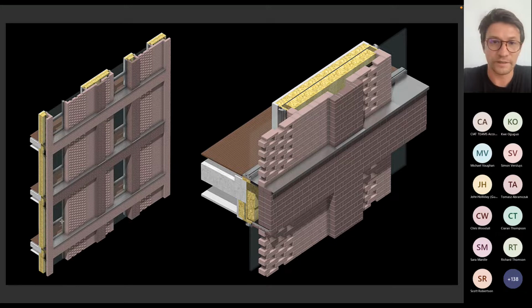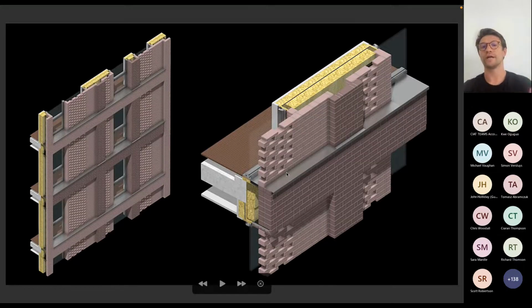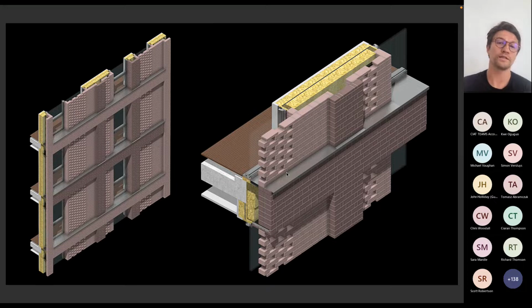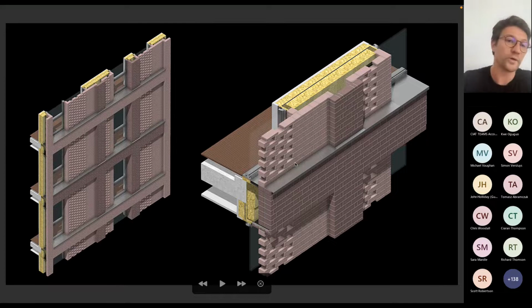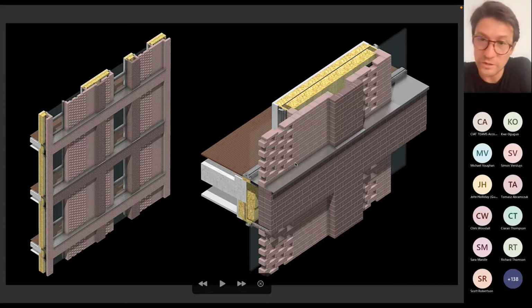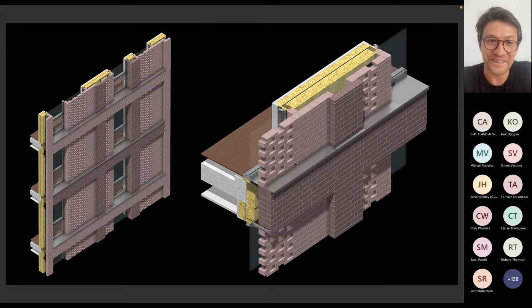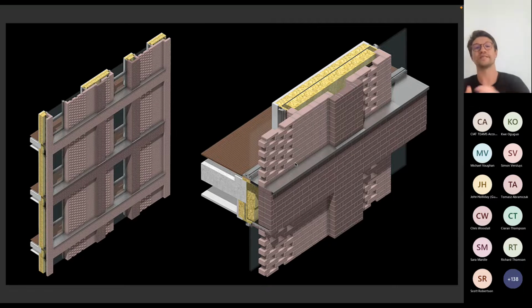I just added this slide here for one simple reason. Sometimes a parameter would be that you can get a complex pattern like this one. However, you can't achieve it as a precast because you cannot get hit and miss brick with a precast concrete element, as you can't cast into thin air. You would still need to rely on stacking bricks on top of one another. And even though this facade bay looks repetitive, with the windows stacked one on top of another, we still have hit and miss brick as solar shading in this particular case study.